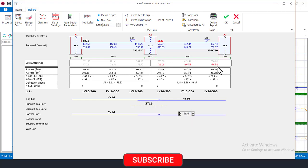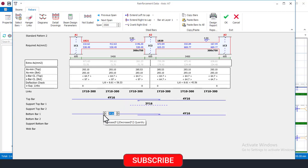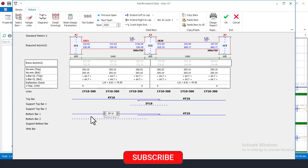And then it is fading here. I'll come here and then increase to 4 numbers, which is okay. And I'll come again right now just to have a good uniformity all the way down, because they have the same length. I can see that these two spans have the same length, which is 5.4 meters, and the same thing here. So, to avoid confusion during the construction of this building, I'll also introduce that to make it 4, so that they will have a smooth lane of reinforcement, 4Y16 at the bottom.